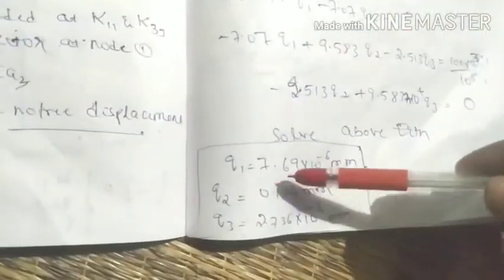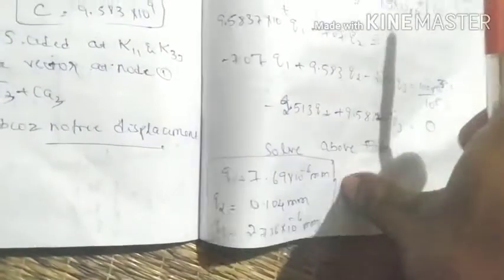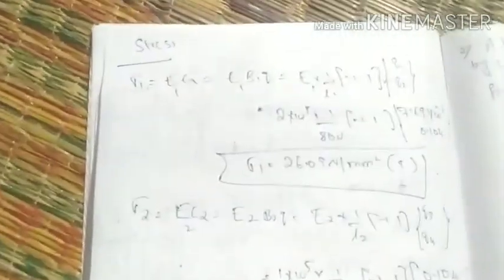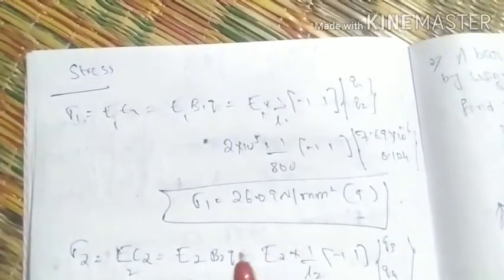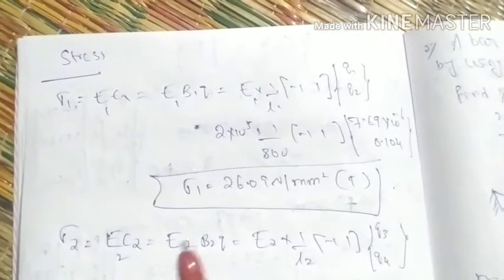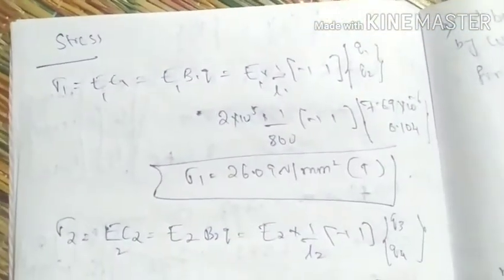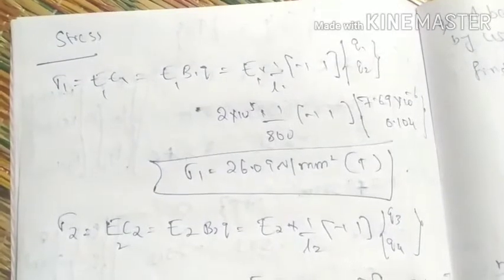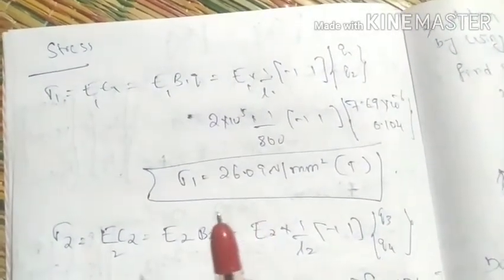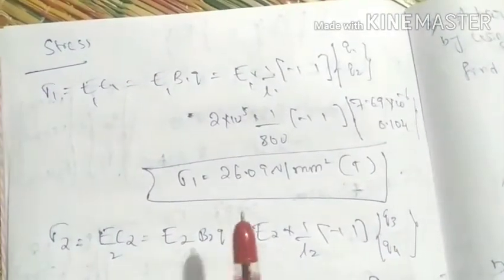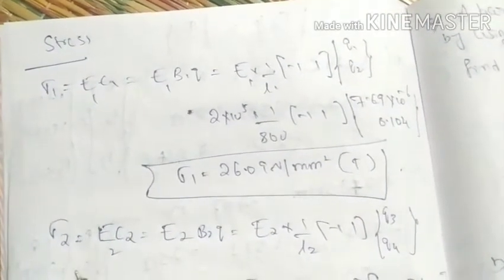In the Gaussian elimination approach we took it directly as 0, but here we calculate that. Because it is not completely 0, some displacement will be there, so that is why the penalty approach will give a more accurate result than the elimination approach. Almost all computer software uses the penalty approach. So in FEA packages they use the penalty approach, because compared to the elimination approach this will give a better result.